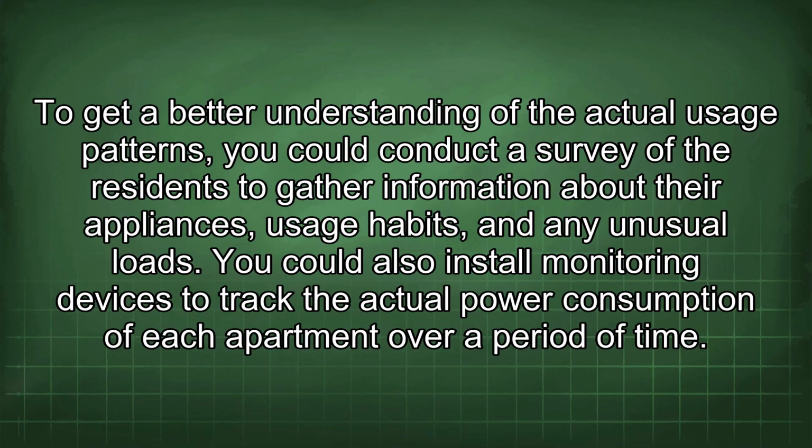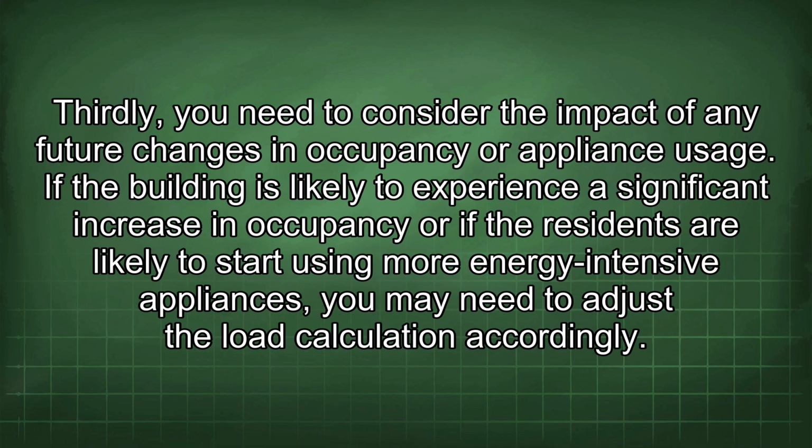You could also install monitoring devices to track the actual power consumption of each apartment over a period of time. Thirdly, you need to consider the impact of any future changes in occupancy or appliance usage. If the building is likely to experience a significant increase in occupancy, or if the residents are likely to start using more energy-intensive appliances, you may need to adjust the load calculation accordingly.